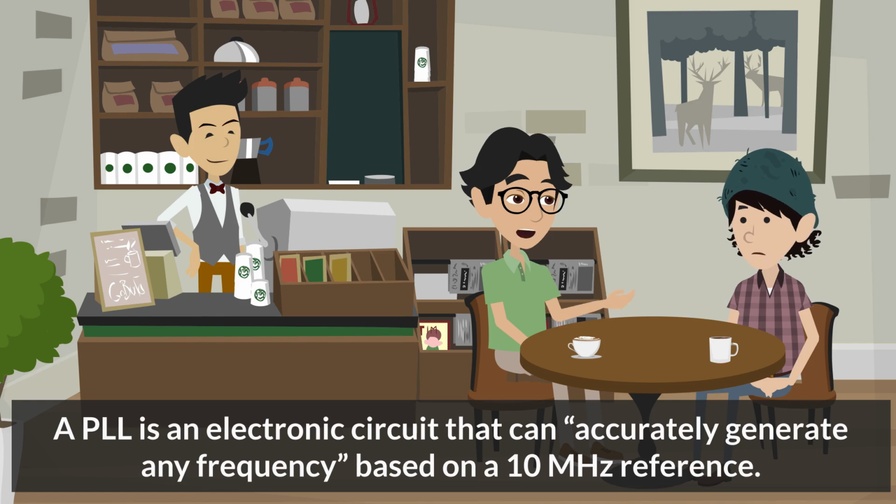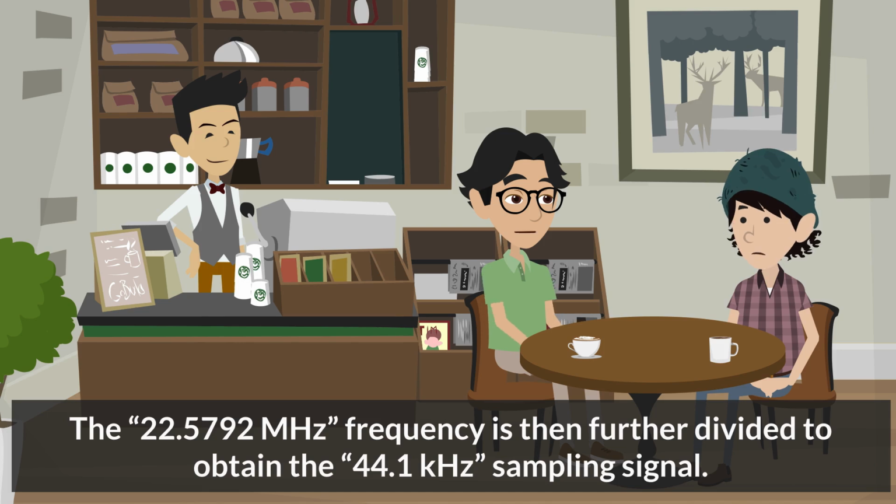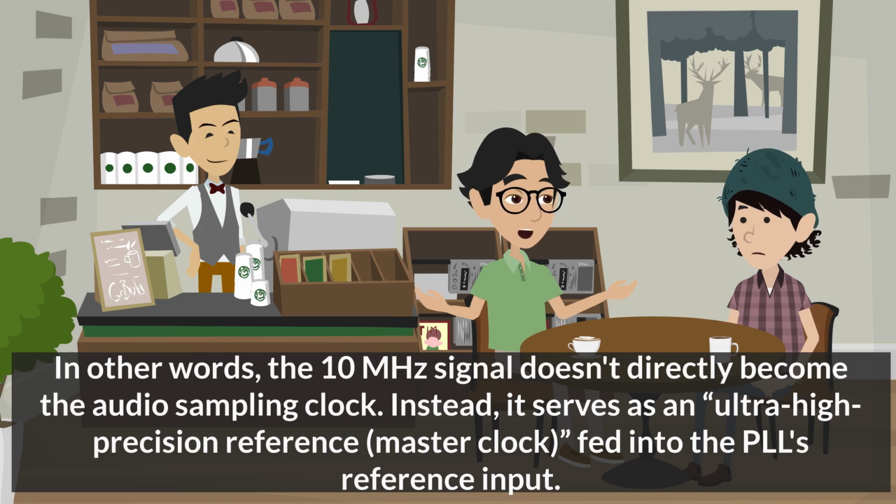A PLL is an electronic circuit that can accurately generate any frequency based on a 10 MHz reference. For example, using the externally supplied 10 MHz as a reference, the DAC internally generates 22.5792 MHz. The 22.5792 MHz frequency is then further divided to obtain the 44.1 kHz sampling signal. In other words, the 10 MHz signal doesn't directly become the audio sampling clock. Instead, it serves as an ultra-high precision reference, master clock, fed into the PLL's reference input.